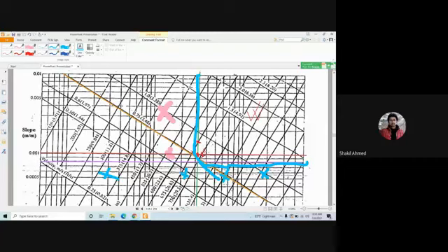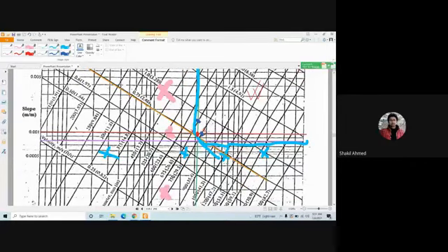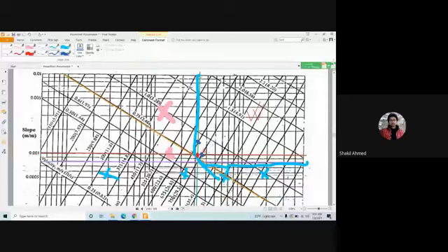So now you have cut at this point. It falls in neither 675 nor 750. So you can either go to this point or to that point. If you are here, your diameter will be 675. If you are here, your diameter will be 750. Since both of these two points are within the permissible zone, you are good, right? So technically, both of these two points are correct. Are you following me? Yes, sir.